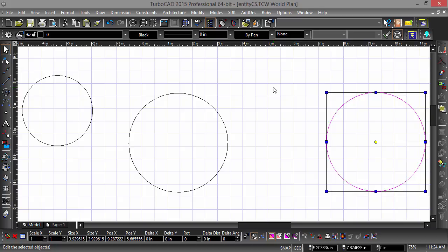So first off, this is a feature, and there are reasons why you would want to have these entities have different coordinate systems and use different coordinate systems in the 2D selector. For instance, if one of these circles was on the face of a cube and I just wanted to move it along that face, it would be very useful to have the coordinate system switch to be that of the 2D object. But that's just one example.